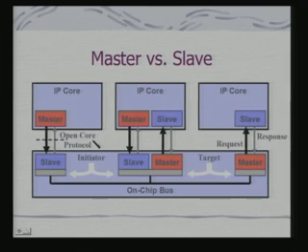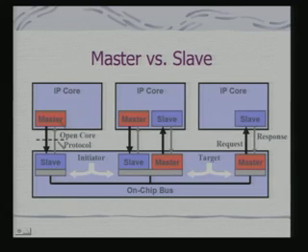So, try to understand this. The AMBA bus had a set of signal definitions as well as a set of transaction definitions. In fact, we had discussed for AHB bus transactions like burst mode transactions, then transactions with security features, split transactions. So, all these transactions are defined as part of that bus definition itself. Here what we are trying to define is basically the protocol for these transactions. So, if you have a standardized protocol, basically the IP cores would be compatible with these protocols.